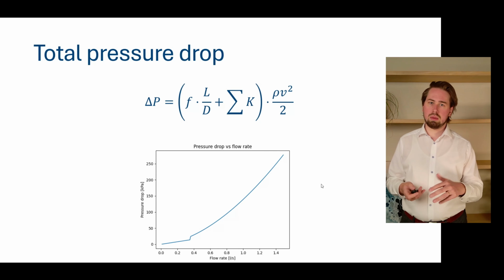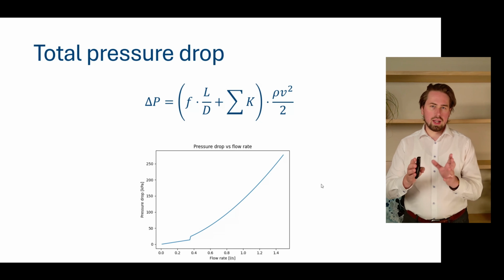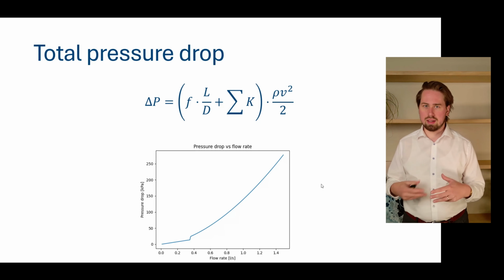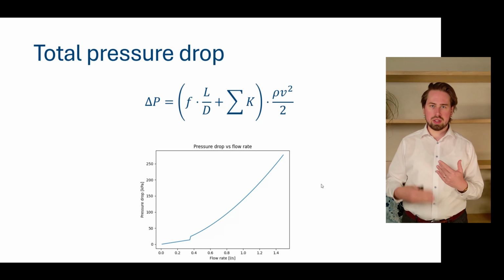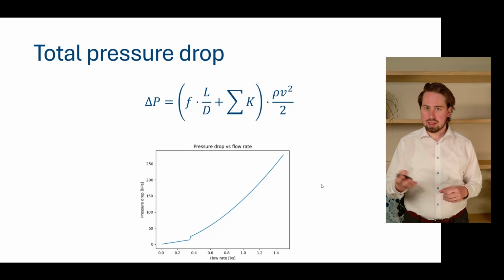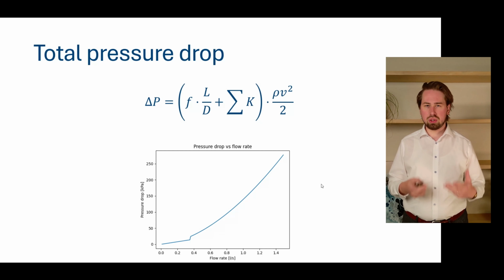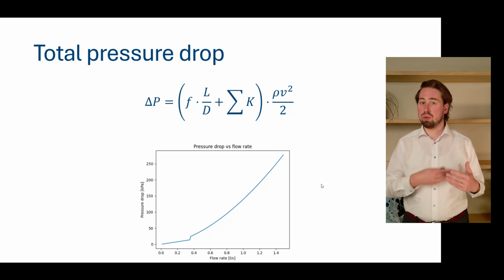And this gave us, as is visible in the slide, this typical quadratic behavior in the flow rate. Here we ended last time. But of course, as we discussed in the last part, part 3.2, the fluid properties, the density, viscosity, the Reynolds number as well, are not constant over time, because the temperatures in a bore field fluctuate, and hence do the fluid properties. This means that our density in this equation, as well as the friction factor, which depends on the Reynolds number, are not constant, they fluctuate. So we do not have one pressure drop, but we actually have a couple of them.